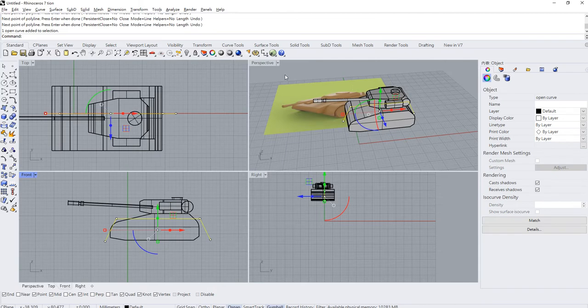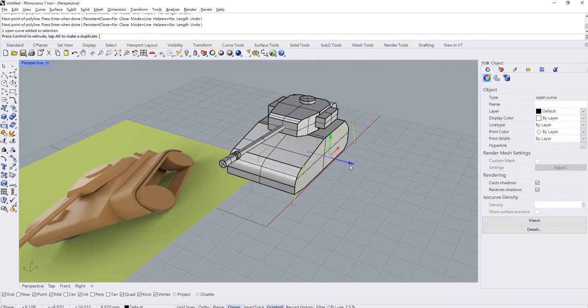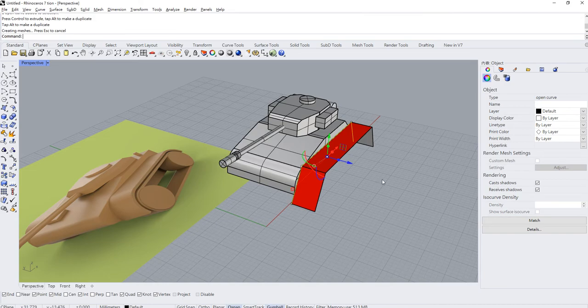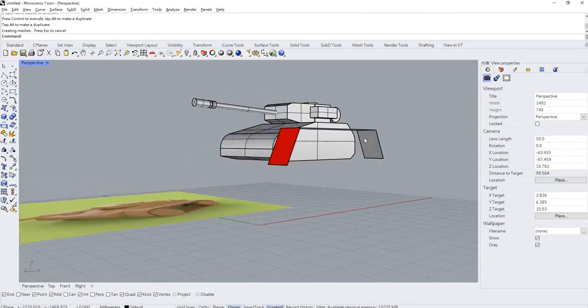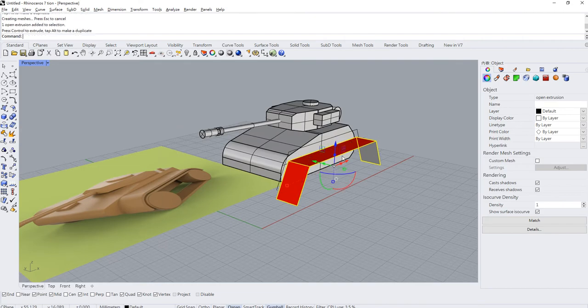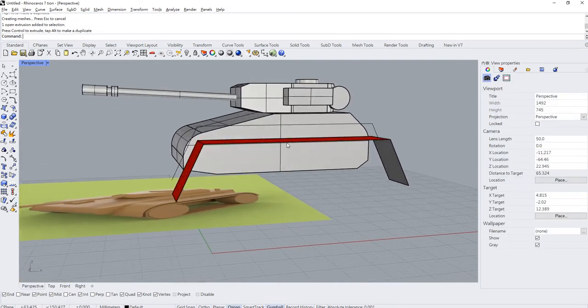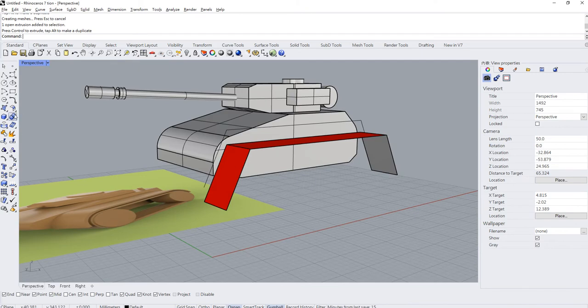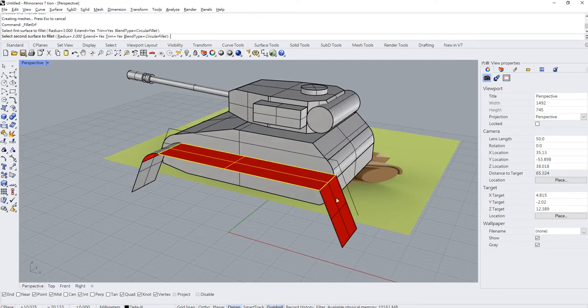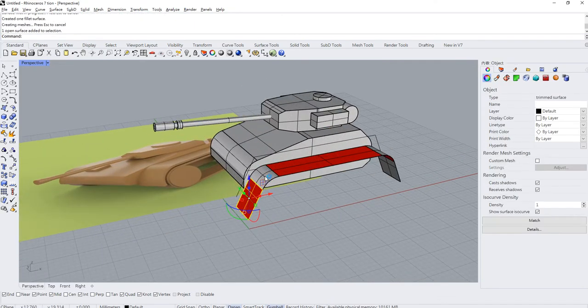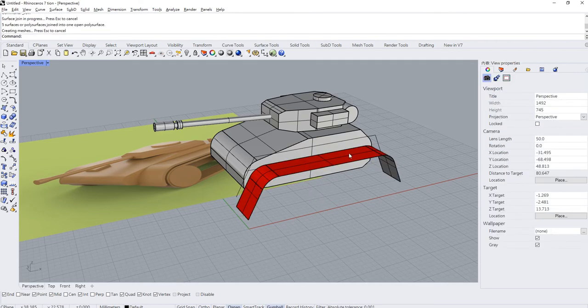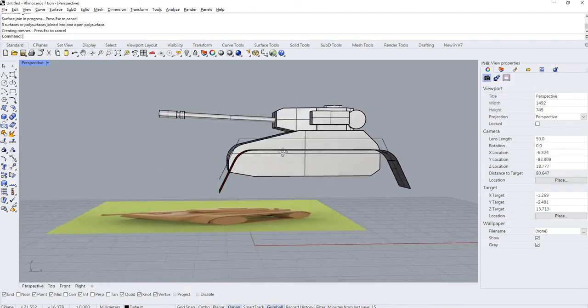And let's go to the perspective view. If you remember, we can just hold on this blue dot and extrude. So now we have this part. Okay, and let's move this one down. Also, I hope we can have some corner right here, so let's go to fill surface. Select this one, press enter again, select both of them. Alright, select all of them and press Ctrl J to join the curve. For now, it's inverted, but it doesn't matter.